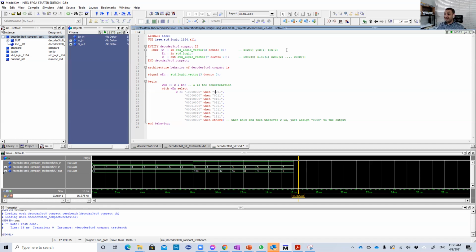So this is 3 zeros, then 1. This is the bit for the enable, the 1, and here is the bit for X, Y, and Z. D will be 6 zeros here when this is minimum term 1, which is 0, 0, 1: X is 0, Y is 0, and Z is 1. Then the enable also must be 1.